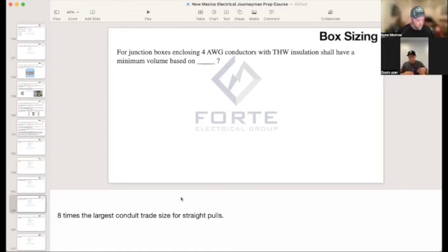All right, let's go over one more thing. Let's go over how many 15 amp breakers are required. I've got a question here that I've practiced with, and it's pretty much what you brought up. It says, how many 15 amp branch circuits are required for lighting of a dwelling unit that's 3 levels with outside dimensions of 40 feet by 23 feet?